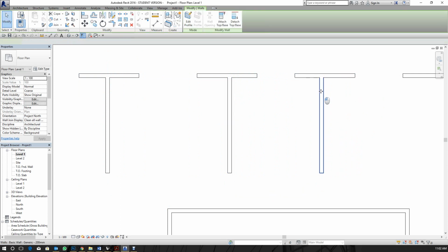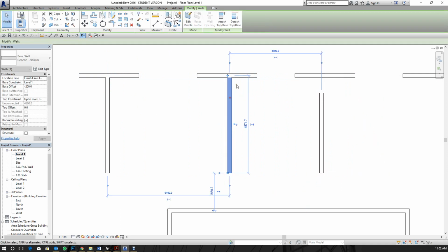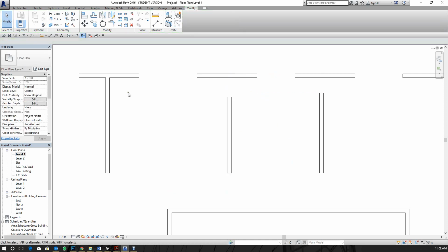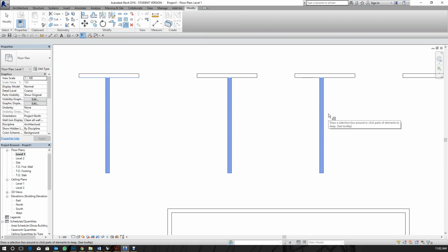And if you needed to do that multiple times, let's do this. Bring that down. Bring that down. So if we had multiple walls that we wanted to extend, then you just use the extend multiple, and go ahead and do that, do that, and do that. And you can extend multiple lines at the same time using the same single reference.